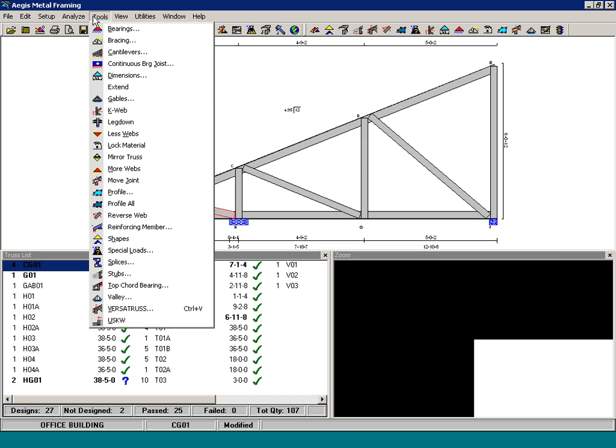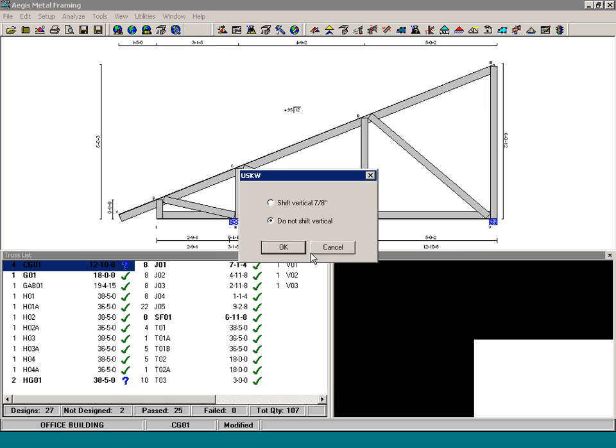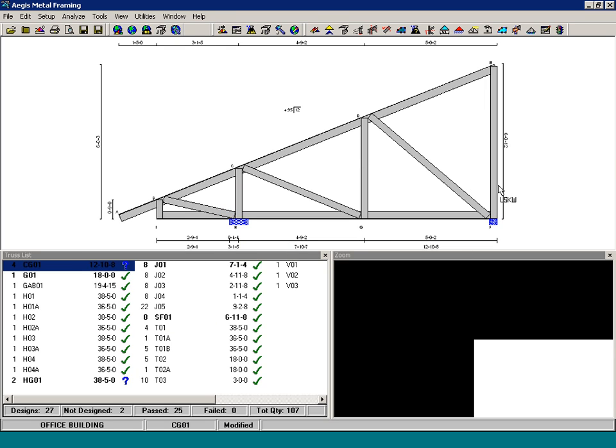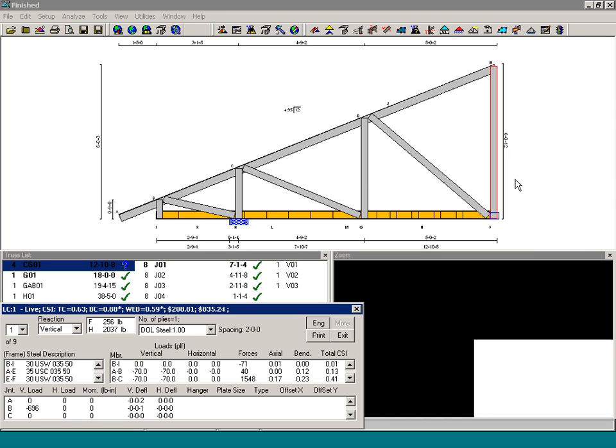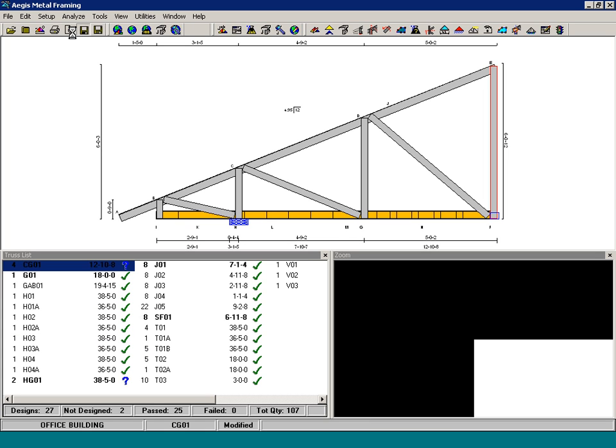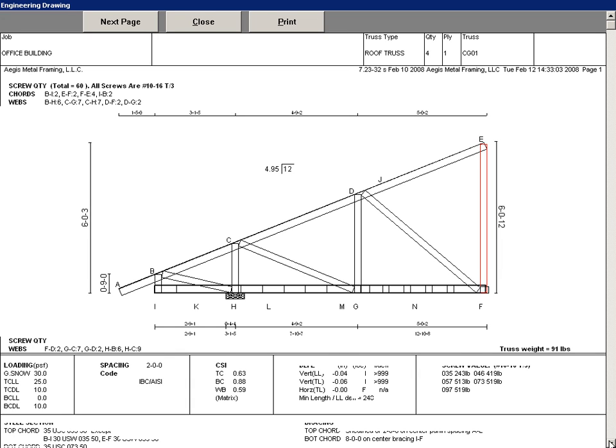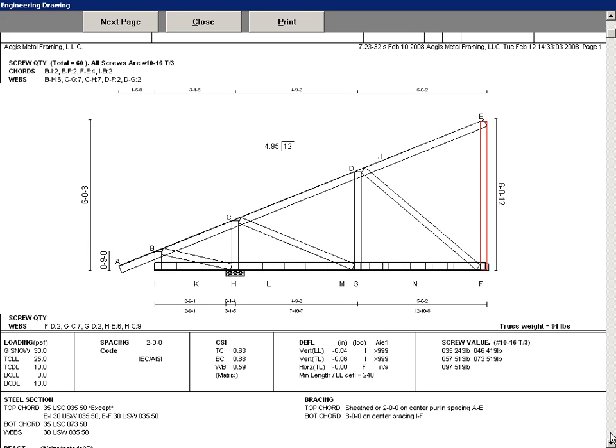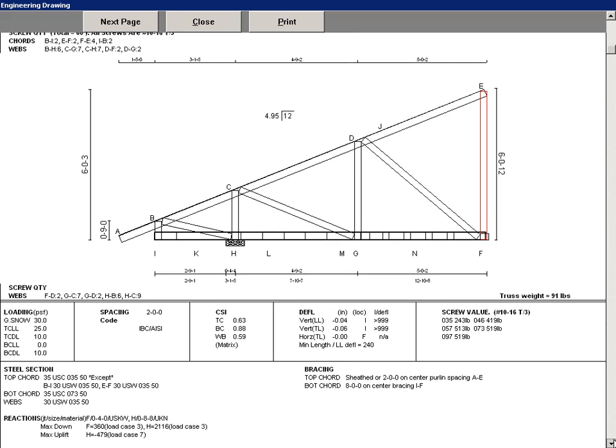Here, the corner girder is analyzed. After analysis, the designer checks the engineering report and shop drawing to confirm the addition of ultraspan girder plate. This USGP will facilitate the attachment of jack trusses to the girder.